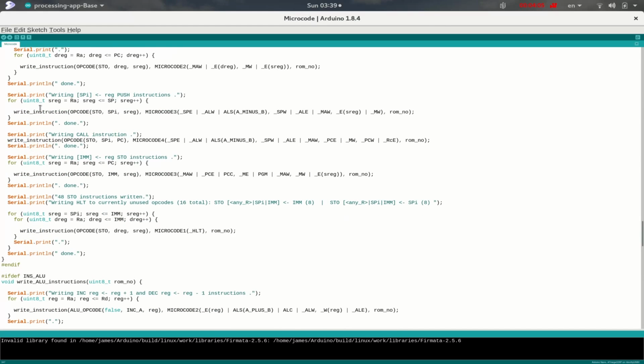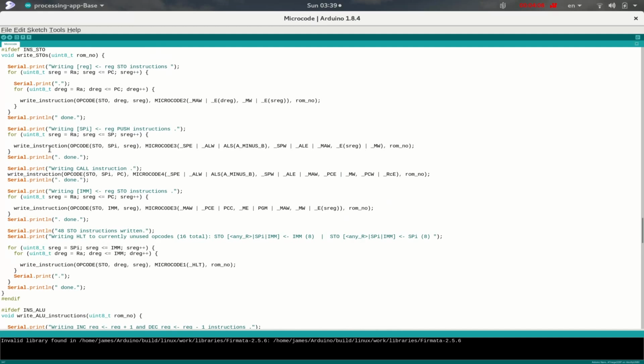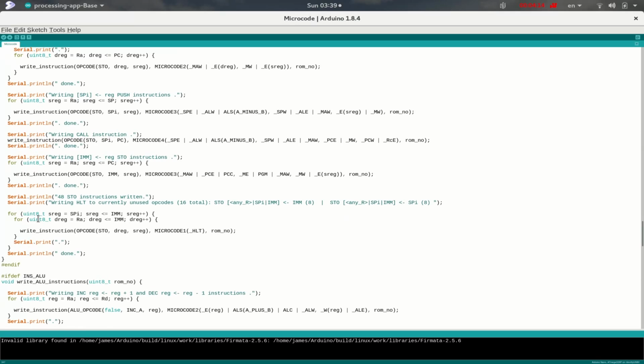Now, once again, we have a whole series of defined store instructions or store class instructions, and so we've written all of those. But then there are certain combinations of register input or output values which we don't support for store instructions. And once again, anything with a source register which is either this automatic increase stack pointer or an immediate operand, we don't support, no matter what the destination register. And so for all of those, these are in effect illegal instructions. Once again we simply instruct the CPU to halt, which is what we do because we don't have any kind of exception handling.